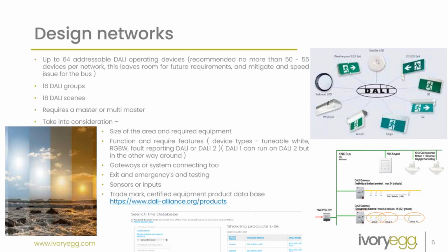A real good tip is, if you're looking at Dali stuff, there's a lot of Dali products on the market. And through my experience, I've got to tell you, only deal with Dali certified products. Okay, this is the only true way you have any recourse if something goes wrong. So any of the gateways, any of the sensors, any of the fittings, they must have the Dali logo. There's two types of Dali logos. There's the Dali logo 1 and the Dali logo 2.